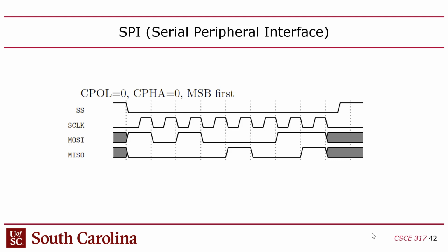That's why it's really important that the slave knows what this timing is too, because it's going to have to start participating in this transaction right from the jump, right after slave select goes low. This all has to happen in one transaction, one exchange, I should say. So in this case, CPHA is 0, meaning read on the first edge, whatever the first edge of the clock may be, depending on CPOL. Make sense? Okay.